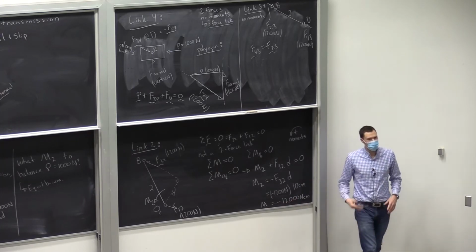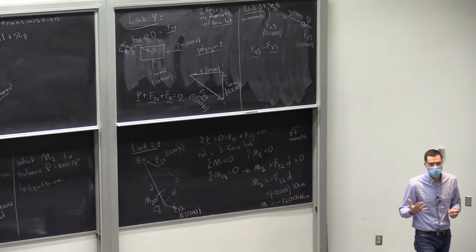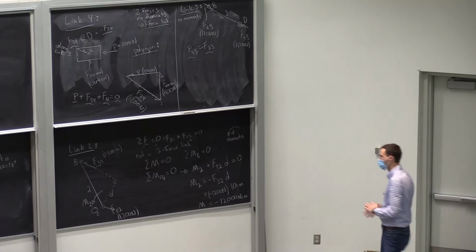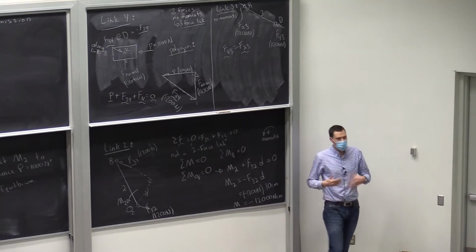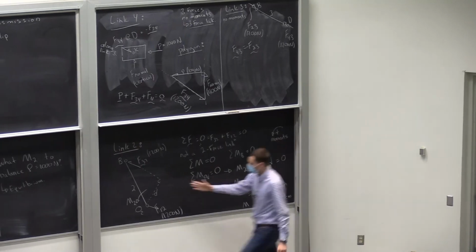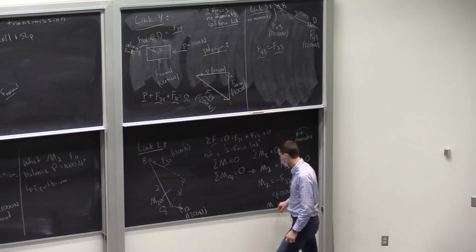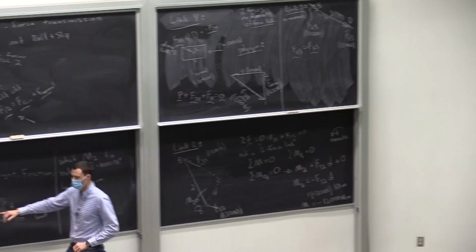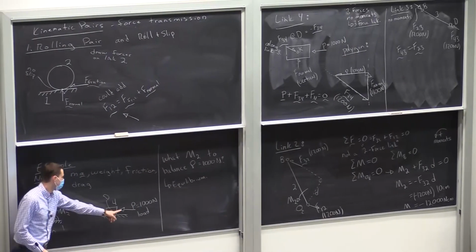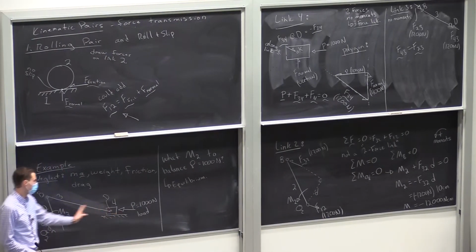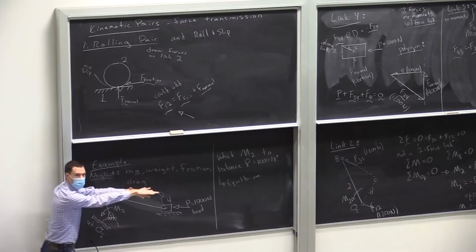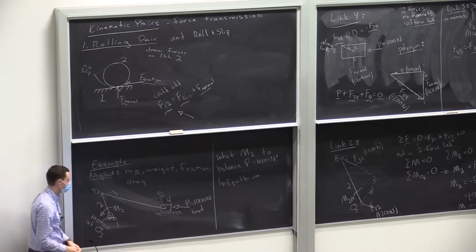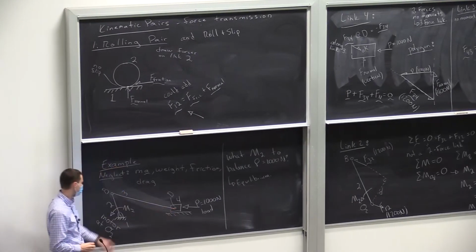So this is a tricky one. We get a negative moment as a result. So we've completed the problem, but the last thing we have to do is interpret this answer. And how do you communicate this? I drew it this way, but we got a negative answer. So that's like I got the direction wrong. And if you think about this, think about you pushing there. To counter you, to balance you pushing that way, I would need to twist link 2 clockwise.